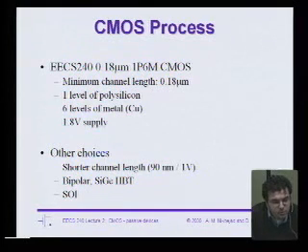Supply voltage is 1.8 volts, which is somewhat of an issue. We'll see how it goes in this class. As the supply voltage gets lower and lower, it gets a lot harder to cascode stages to get high gain, and you have to start playing other tricks to really improve the gain of op amps. And that's part of this course. That's what we're going to teach you guys.